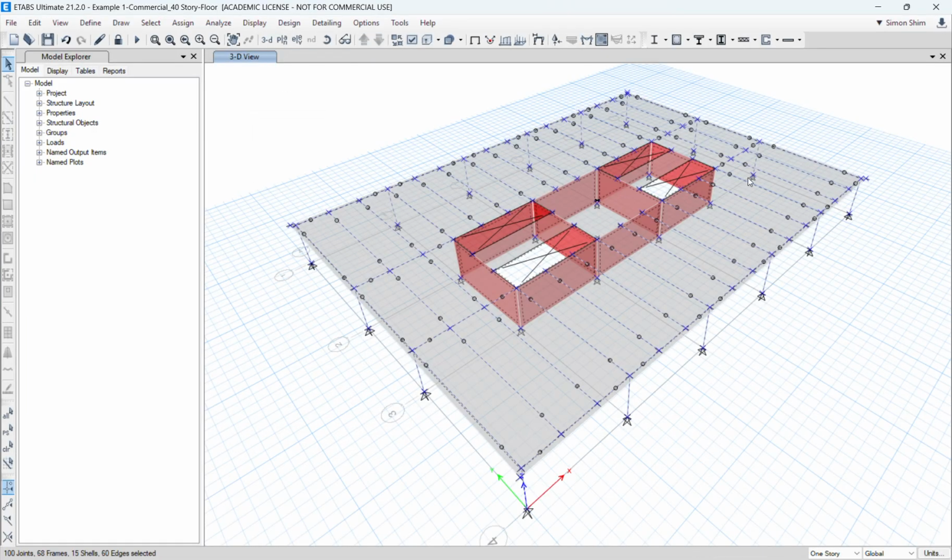So, okay, there are a few things you can do. I think first of all, today everybody already copied the entire wall or building all the way up to the 40 story without modifying the wall, right? The wall layout. We actually segmented, basically cut the wall piece by piece by 3 by 1, and you could do that too. But I think a better workflow is I'm going to just modify the first typical floor and then copy it 40 times.